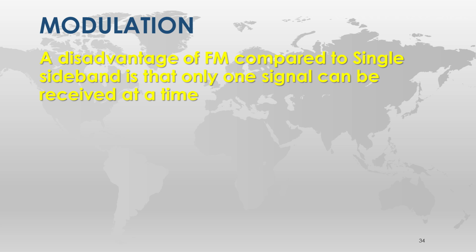Now, if you've got two guys on sideband talking, you may not be able to understand it, because they'll be stepping on each other, but you still receive both signals. So if you have somebody on lower sideband talking at the same frequency as somebody on upper sideband, can you hear them both? It depends on how good your filters are, but if you're on lower sideband and he's on upper, you're using different parts of the spectrum. So you wouldn't hear it, but somebody else could hear both if the conversations were going on side by side, one lower, one upper.